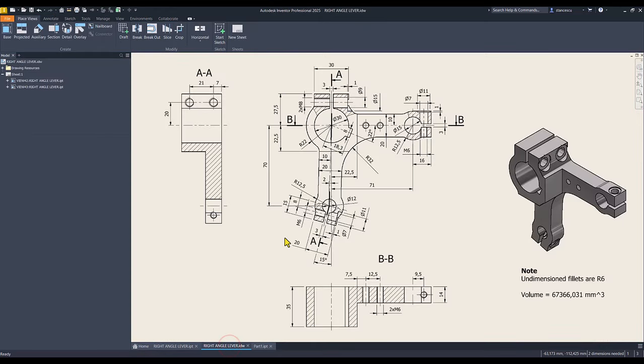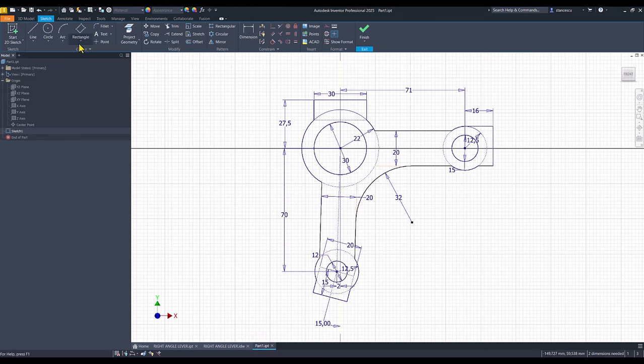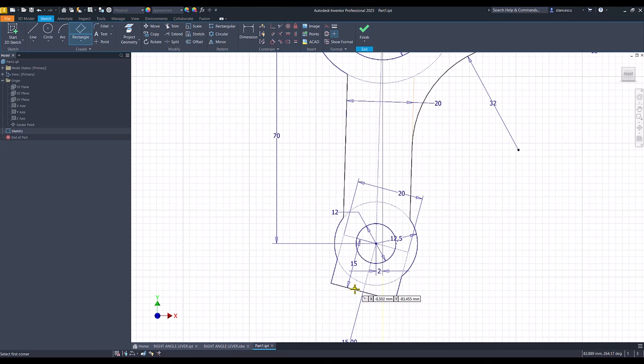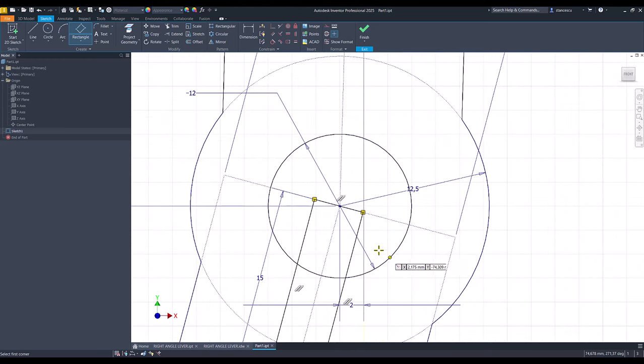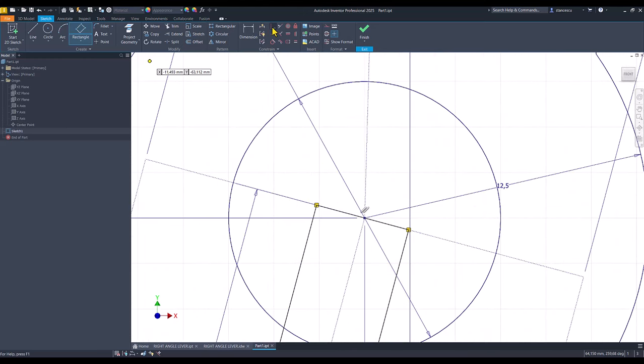Good. Now the cuts. You see 3 millimeters here, 3 here, and also 3 here. I use this firstly because I place a rectangle going to this center. I make coincident the midpoint of this with this center.